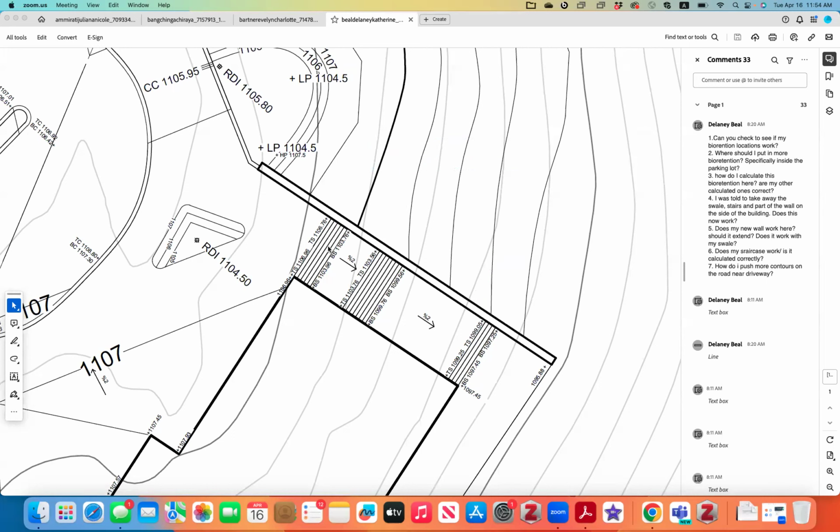The calculation seems reasonable. I would not start with exactly the corner. People need anticipation before they get into the stairs, right? They will trip if you make the first one flush with the corner. So I would start at least one more step into the same thing. I would move this inside this one, the first step there. Okay, so that's the stairs.